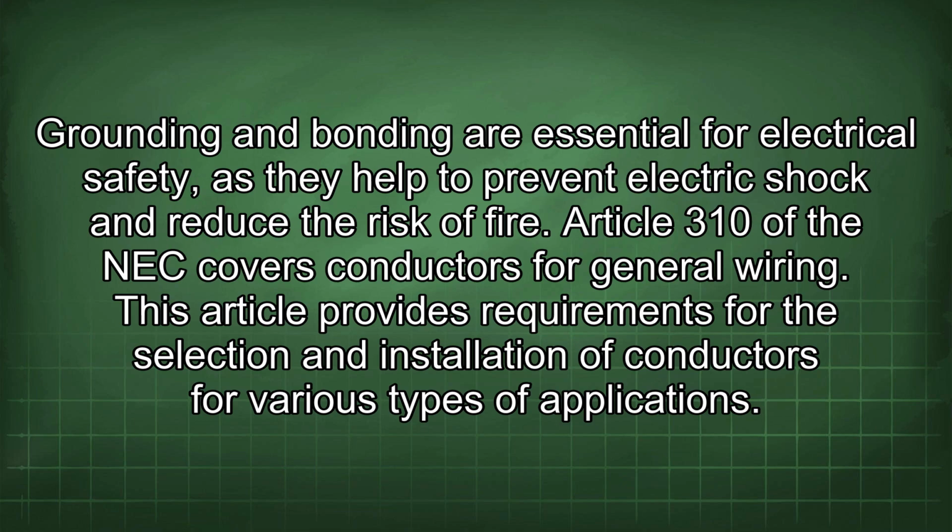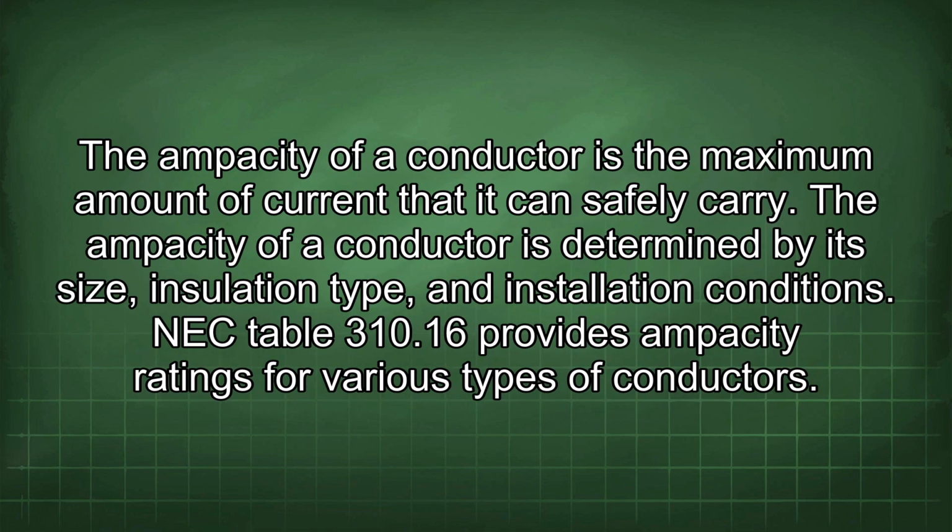This article provides requirements for the selection and installation of conductors for various types of applications. The ampacity of a conductor is the maximum amount of current that it can safely carry. The ampacity of a conductor is determined by its size, insulation type, and installation conditions. NEC Table 310.16 provides ampacity ratings for various types of conductors.